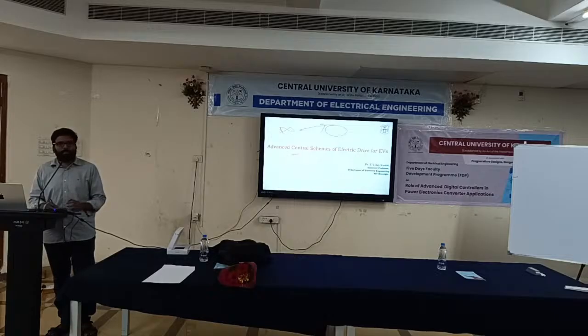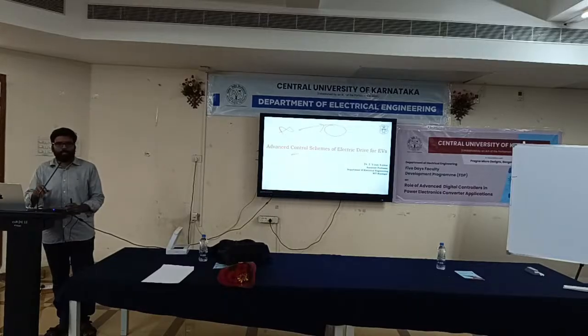Heating effect is very less. If heating effect is less, the advantage is you can operate for more time. Otherwise, extra cooling mechanism is required if it is not in circular shape. So to minimize the heating effect and the centrifugal forces acting on the rotor surface, intentionally all dynamic machines are made in circular shape.